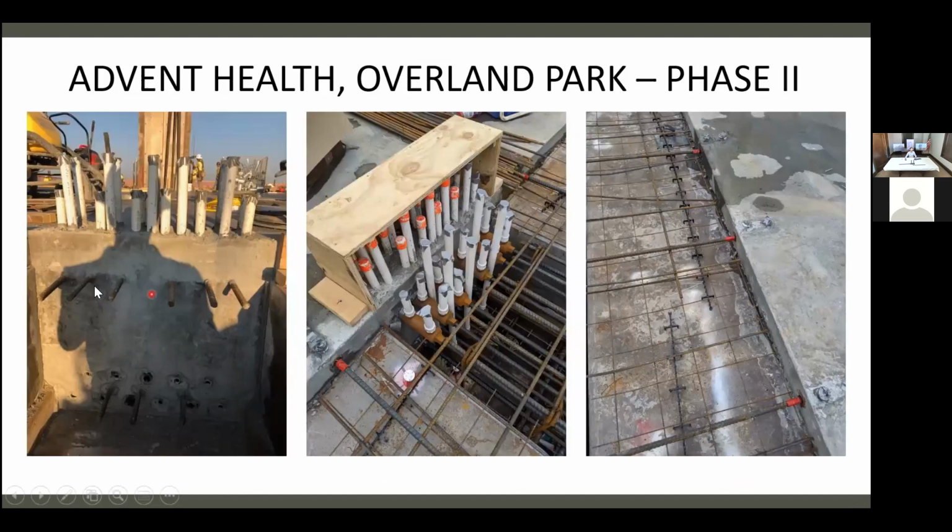So on the left-hand side, this rebar that's sticking out right now, on the bottom, you can see the holes where the continuation bar is gonna go in. But these rebar that are sticking out, we have our couplers that are gonna get put on there, as you can see in the middle picture. So we always got a solution. This engineer was just giddy working with this. He loved it, saved so much time and effort.